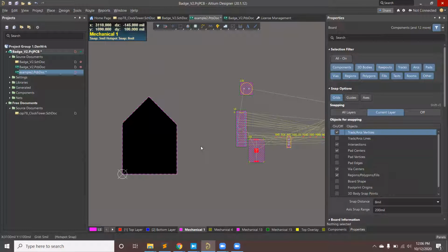Another helpful thing, I think I mentioned this in the component making, but you can press the button Q, and that will switch you to metric units, so you can switch back to freedom units, Q, millimeters and mils. Usually I place components in millimeters, and then I place traces in mils, because that's what manufacturers are going to base their dimensions off of, but it doesn't really matter. You can do whatever you want.